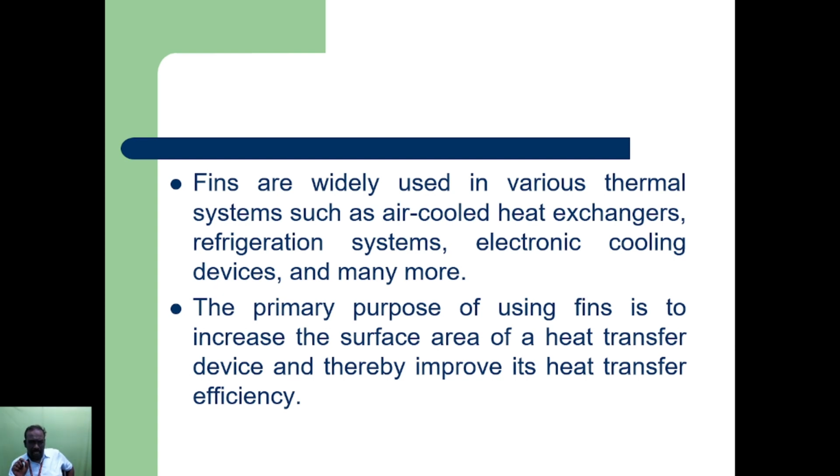The primary purpose of fins is to increase the surface area for heat transfer in a device, thereby improving heat transfer and efficiency. Adding area increases the heat transfer by the convection mode. Fins are used in air cooled heat exchangers, refrigeration systems, electronic cooling devices, and many more. We also consider the efficiency and the effectiveness of fins.